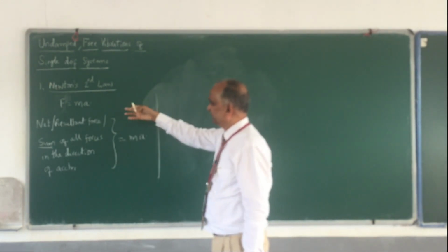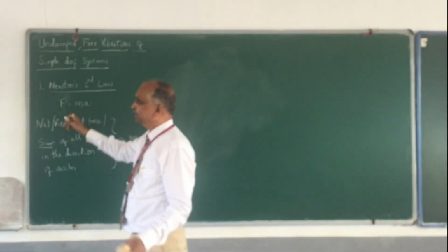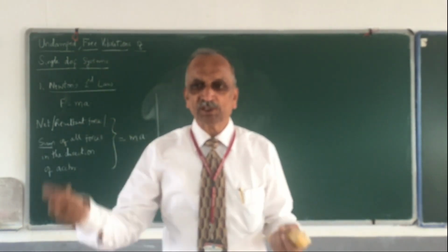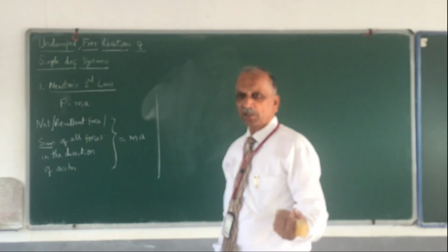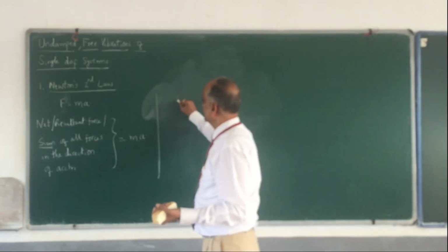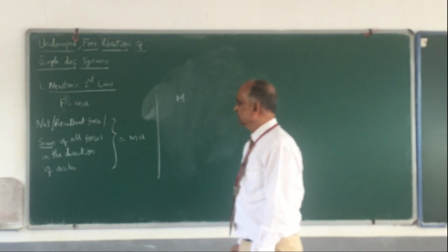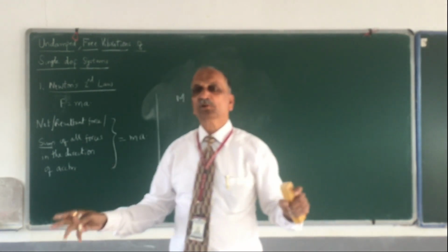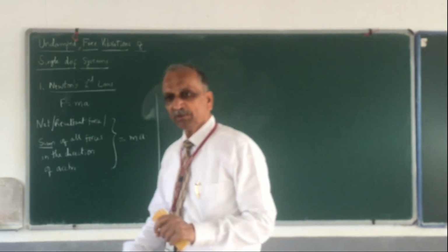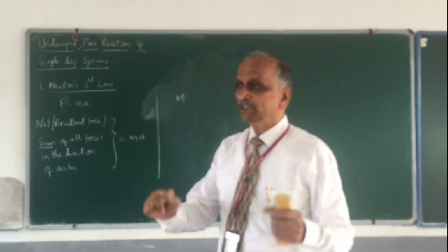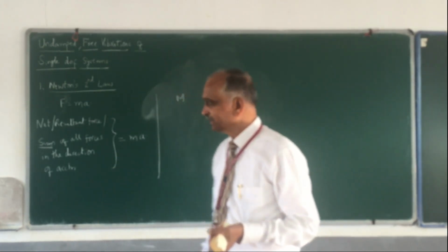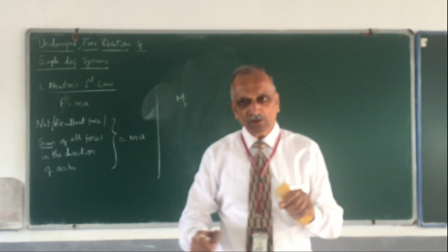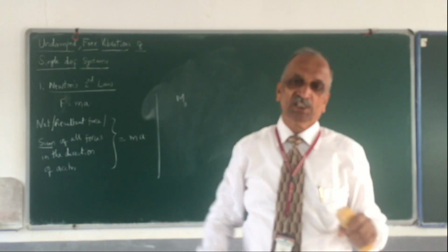The expression is very similar. F, as I said, is a force which will make the body move along a straight line. Then what is responsible for the rotation? It is moment or couple or torque. So let me say it is moment. Moment is responsible for rotation. Whenever we say moment, we always say moment about what point, about what axis. Say M about O. What is O? O is the point of the body about which the rotation is taking place.